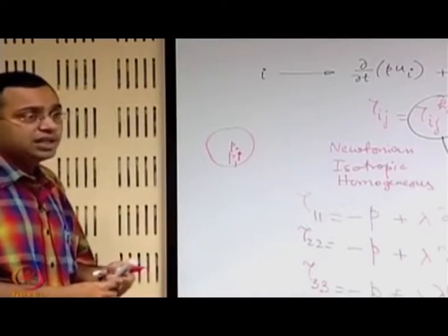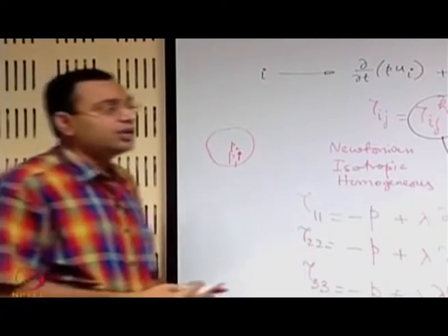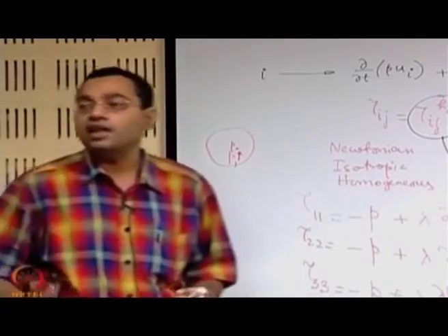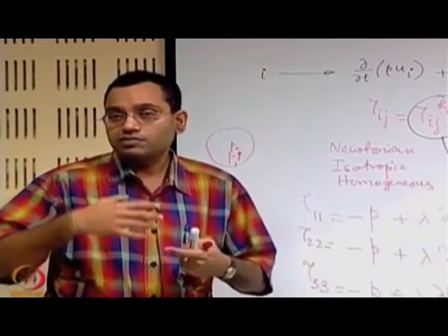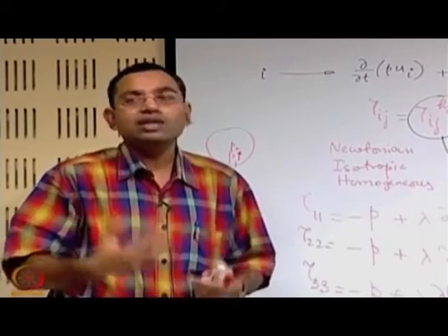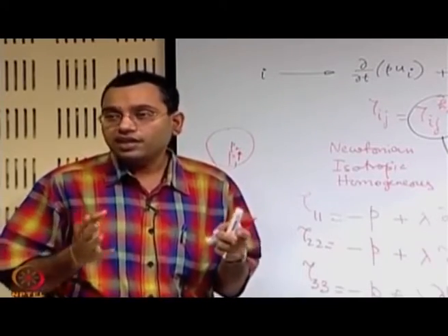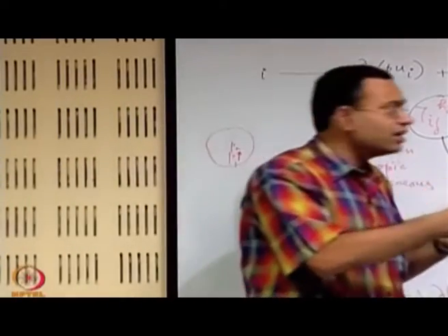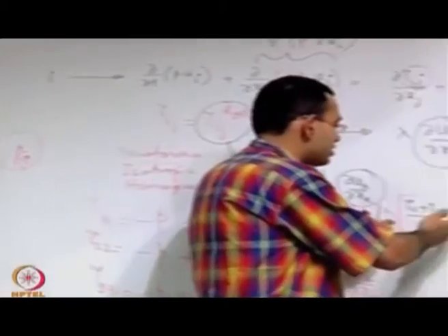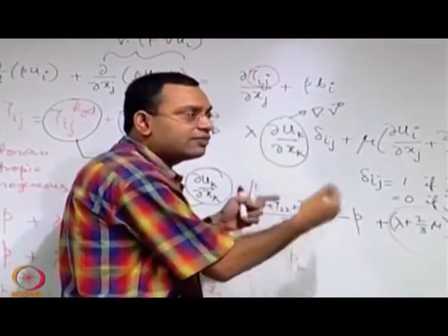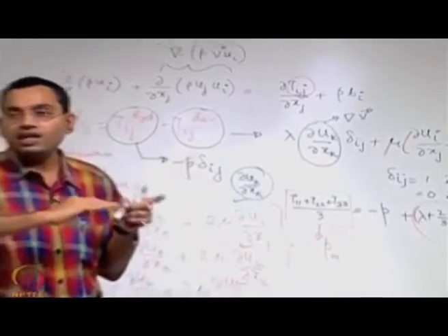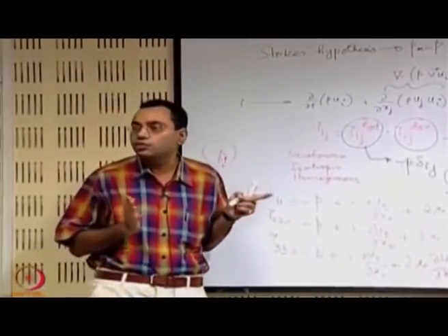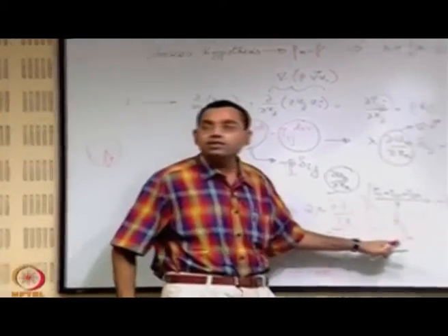So mechanical pressure may not be equal to the thermodynamic pressure if the time scale of change is faster than the relaxation time scale. If the time scale of change is slower than the relaxation time scale, then whatever is the change in thermodynamic state, the system adjusts to that, eventually that mode is entirely transformed into a translational mode of energy reflected in the form of a mechanical pressure. So the entire vibrational and rotational modes of energy should also be dumped in the form of a sole translational mode of energy, and that will be manifested in the form of mechanical pressure.